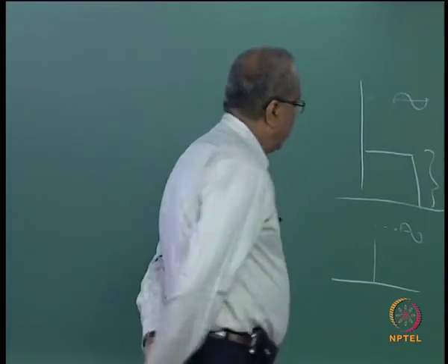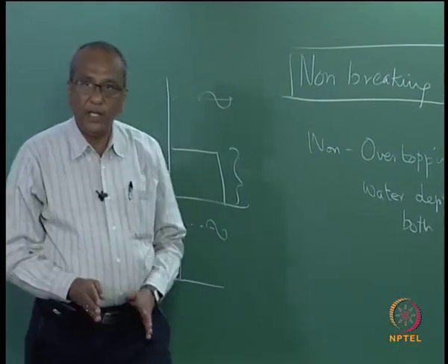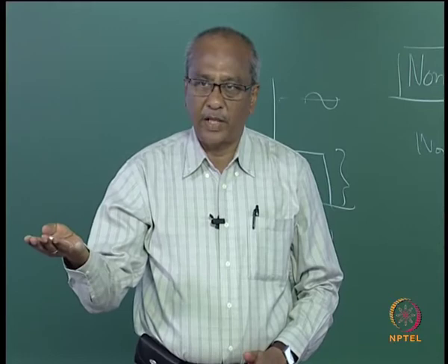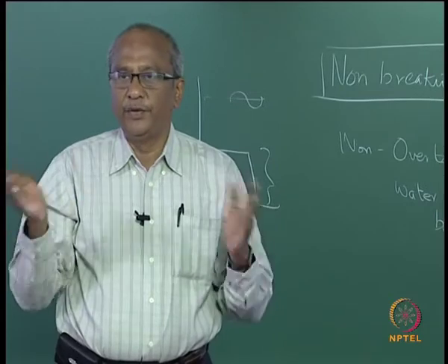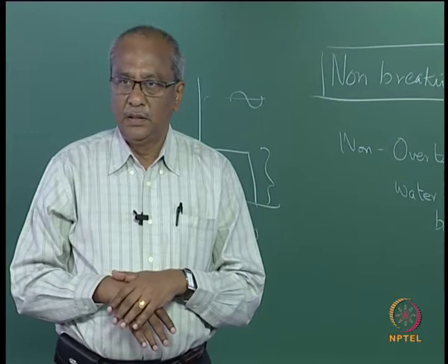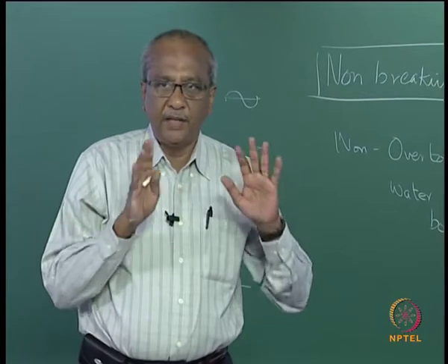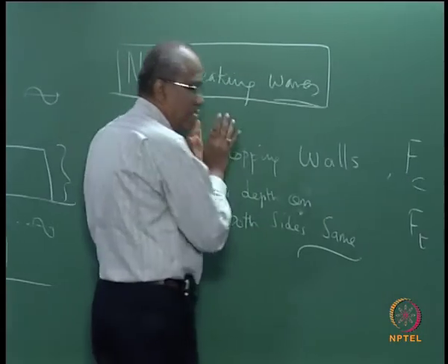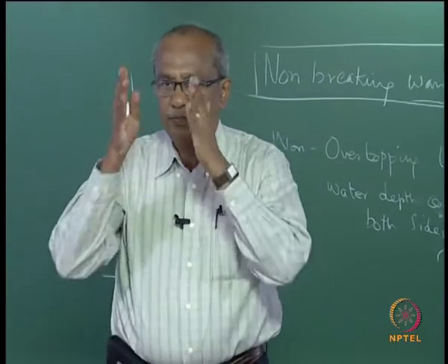Okay. Then finally what did we do? We took a vertical wall wherein on one side you have a particular water depth and on the other side maybe a lesser water depth, and then we looked at how the forces can vary, and also the moments. So I think we have completed most of the scenarios that you can come across in dealing with wave forces on vertical wall structures.